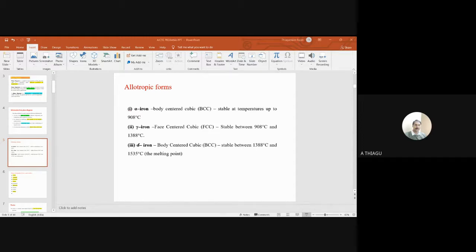You look at the change. At 750 degrees, I heated the sample for 3 hours. The structure of the metal is a complete homogeneous austenite. The symbol will be gamma. So the process is called austenitizing.